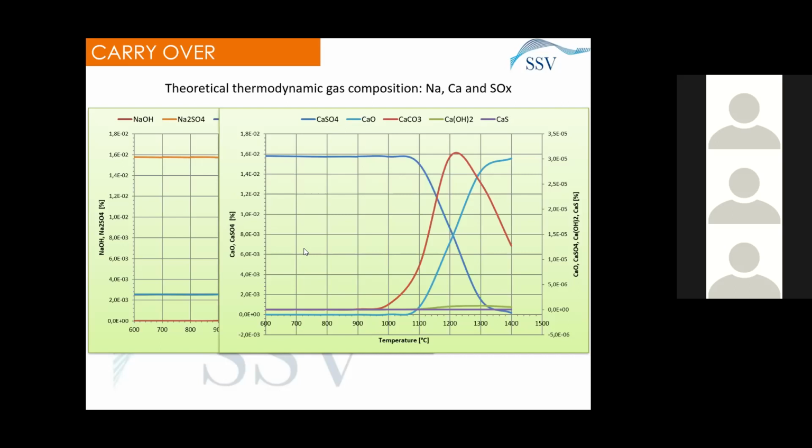So I cannot give one single exact answer to this question, because this aspect is also affected by the size of the furnace itself. If I have a furnace with a pull rate of 200 tons per day, versus a furnace where the pull is 500 tons per day, there are differences in the shape of the flames, and this also affects the angle used for the burners. So I do not have an optimal angle to give you.